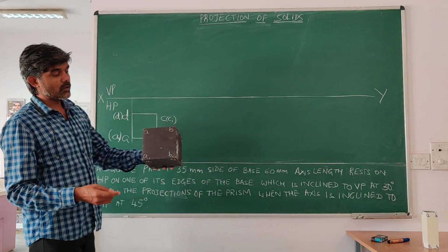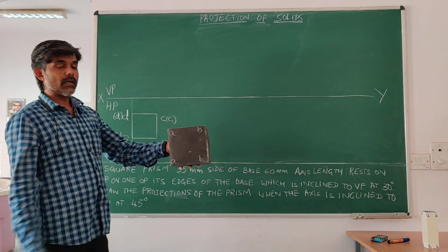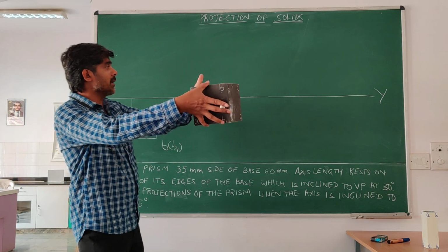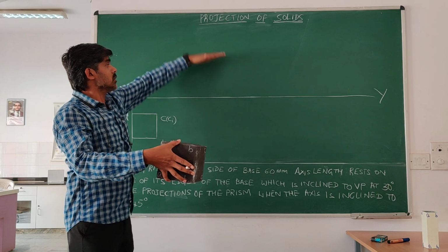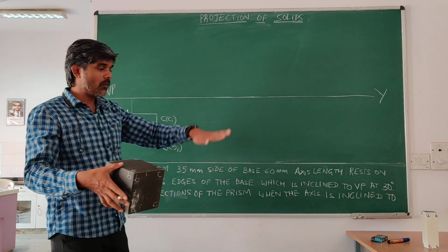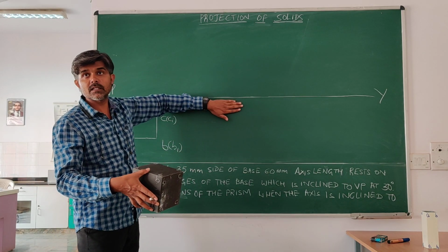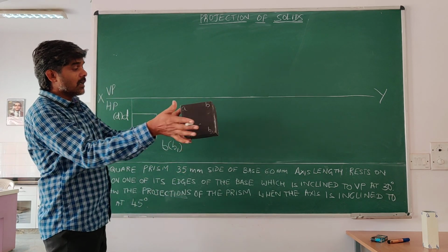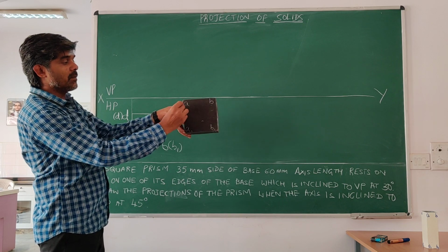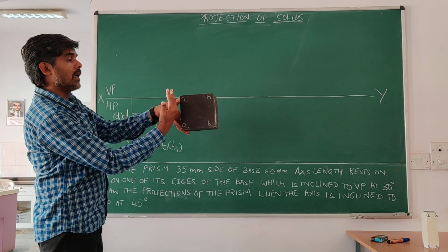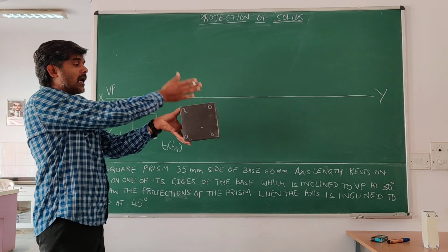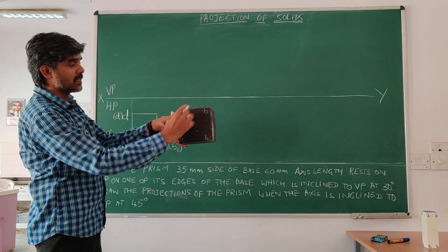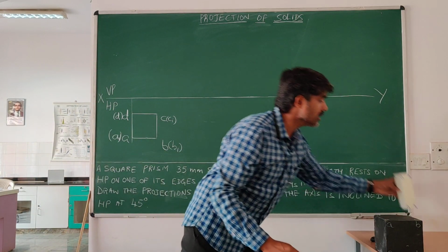Next, we want to get the front view. To get the front view, the observer will see from here. What he sees is the projection we will be getting on the wall. Above this is the wall, below this is the floor, which is rotated and has become like this. Now, when the observer sees from here, he will be seeing this space. The spaces perpendicular to it he can't see, and the face behind is also hidden by this space.